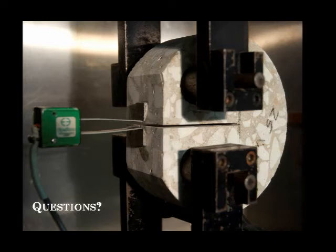Yeah, he brings up a good point, but as long as your equations account for the CMOD opening up, I'm not sure it makes a difference in the K1C calculation. It wouldn't make a difference in the total fracture energy. Yeah, the total fracture energy would be the same. But K1C, it could make a difference.